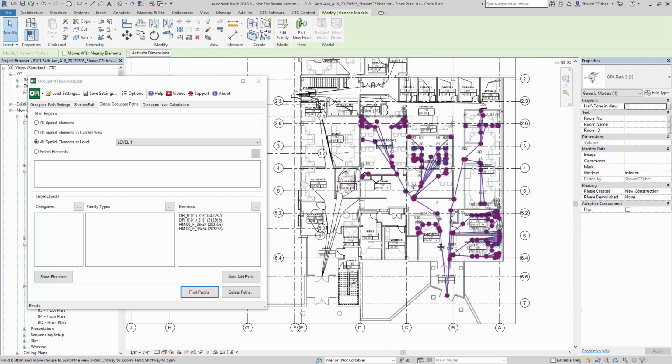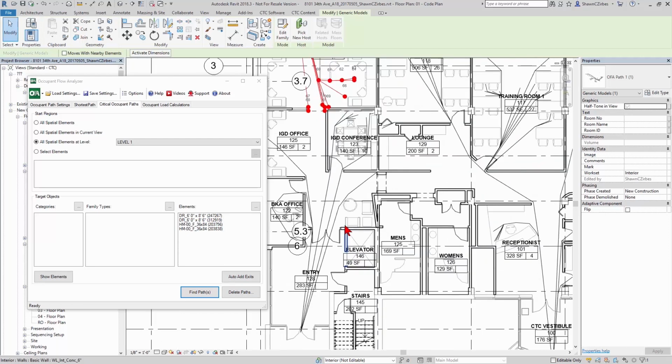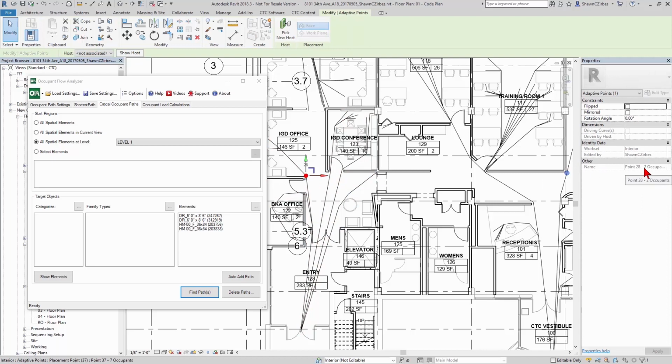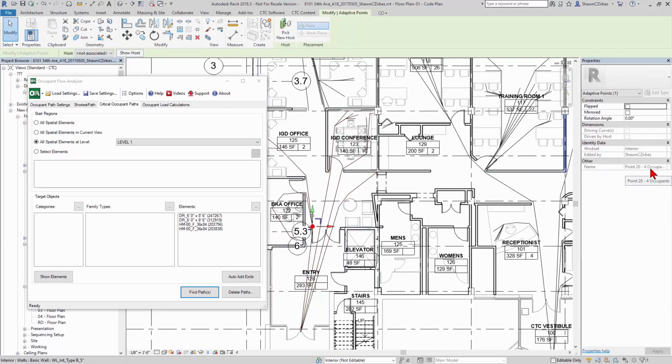In my project out here, I can actually see the individual egress zones. Shortest paths all being calculated to the individual points of egress. If I have any questions about what the egress is at a specific point, or the number of people at specific points, I can simply tab through and understand for that point what the number of people are passing through there. In this case, 2 occupants at this point. And if I go down a little bit further right here, I can tab into and understand the occupant numbers at the next point. Sometimes you have to tab a little far, but you can always find out, in this case, 4 occupants, and I think at this one it is 15 at the final point of egress for this particular building.